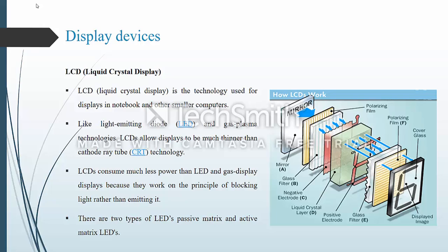The grooves will cause the first layer of the molecules to align with the filter's orientation. Then add the second piece of glass with polarizing film at a right angle to the first piece. Each successive layer of TN molecules will gradually twist until the uppermost layer is at a 90-degree angle to the bottom, matching the polarized glass filters.